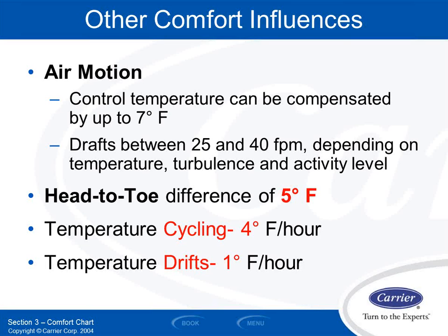So if you looked at the tables for people and square footage, and it said you had to bring in 1,000 CFM of outside air, but you designed your system for warmer than 15-degree discharge air above the space, then you have to bring in 1,200 CFM of fresh air instead of 1,000, because they recognize that when the air is really hot, it short cycles and goes right back out the return. That's a pretty big deal on the heating side if you can avoid that.